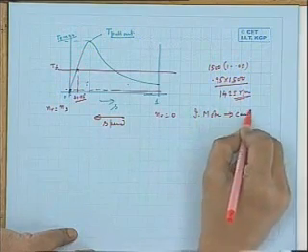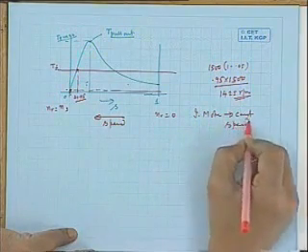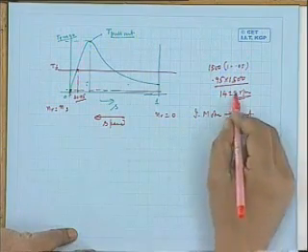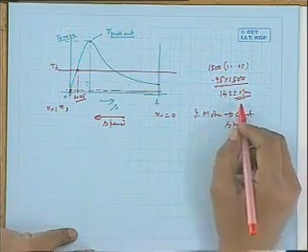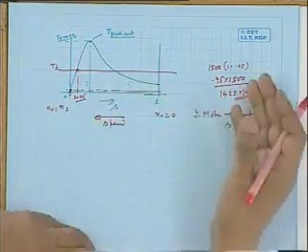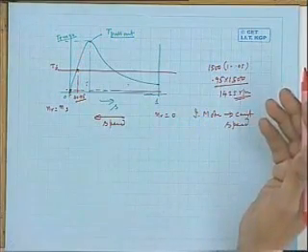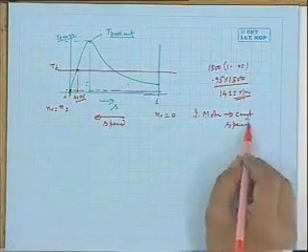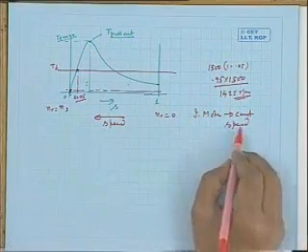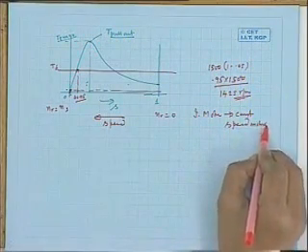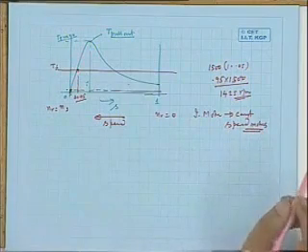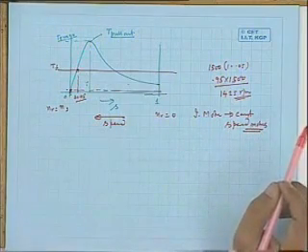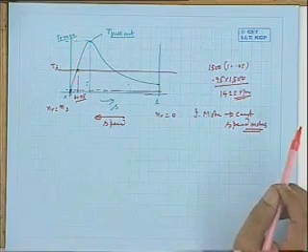Are you getting this point? Induction motors are generally called constant speed motors. Constant speed means, of course, approximately, because of this fact. At no load condition, the speed will be very close to 1500 rpm. And at full load, the operating slip is about 4 to 5%, so the variation of speed is about 75 rpm. So induction motors are sometimes called constant speed motors.